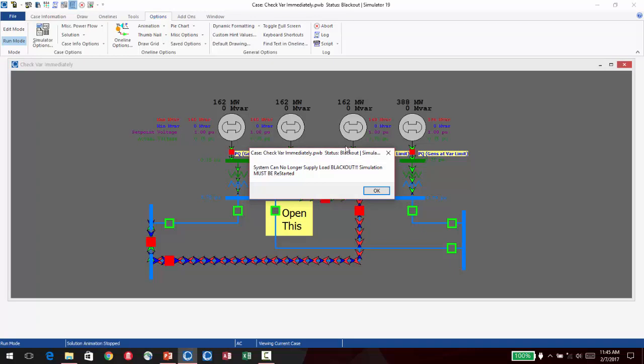What about the generator megavar support? Notice that all generators are still operating at 0 megavars, so none of them have tried to move. The power flow started with the generator buses flagged as PQ buses because they started at their minimum megavar. If they were operating with more VARs providing more support, they might have prevented the collapse, but the inner power